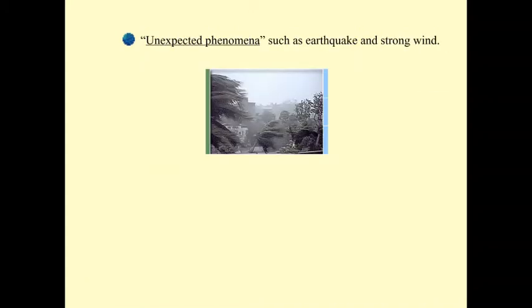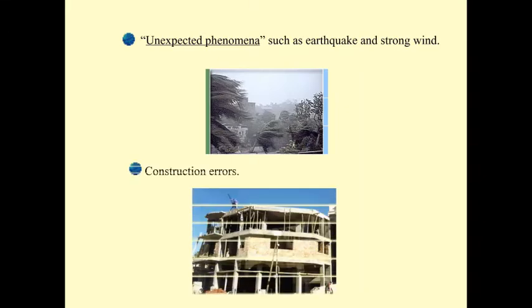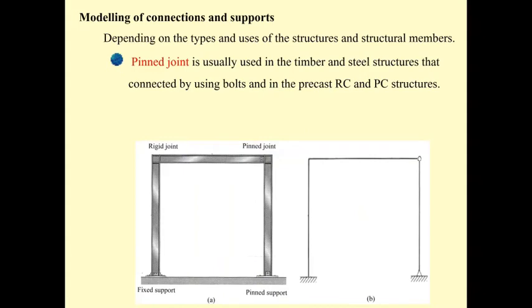And the factor of safety is also important, not only due to the behavior of the structure, but maybe due to unexpected phenomena such as earthquake and wind. Also, it is going to cover construction errors that may occur from time to time.